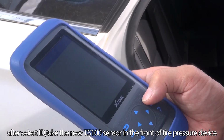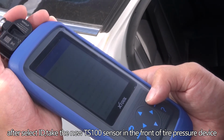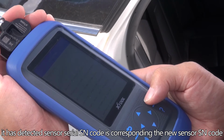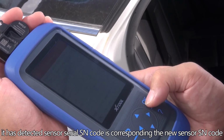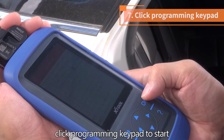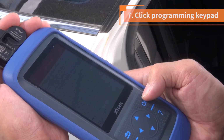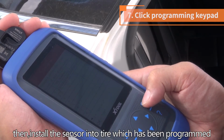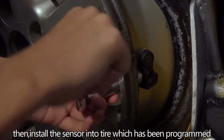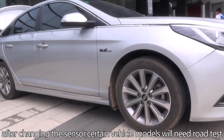After selecting ID, take the new TS100 sensor in front of the tire pressure device, enter programming interface. It has detected the sensor serial SN code is corresponding to the new sensor SN code. Click programming keypad to start writing ID into the new sensor. Then, install the sensor into the tire which has been programmed. After changing the sensor, certain vehicle models will need a road test.